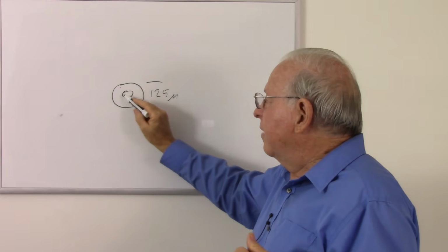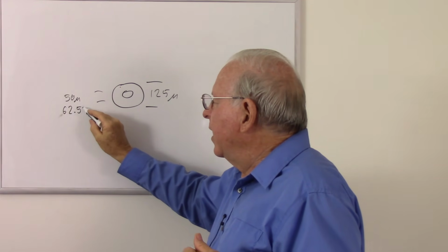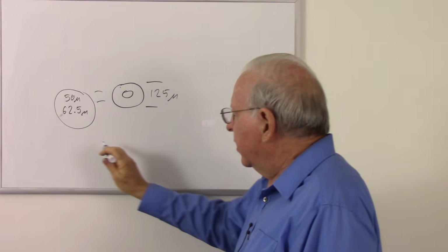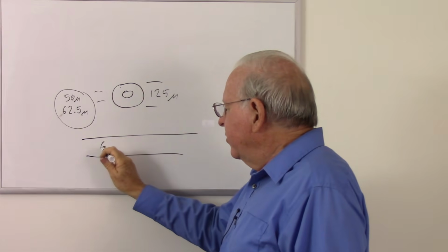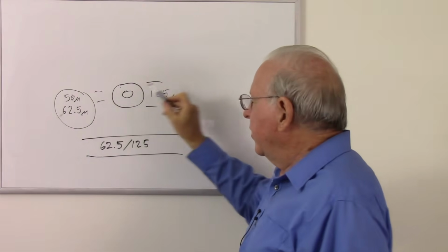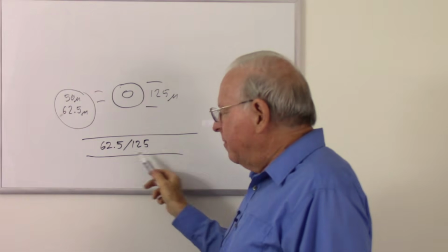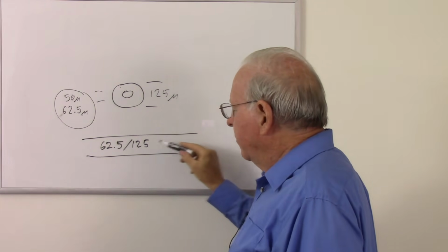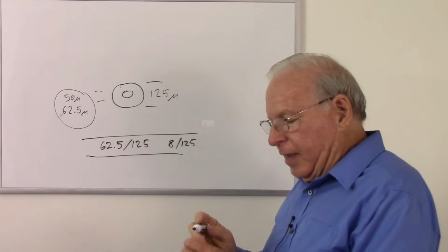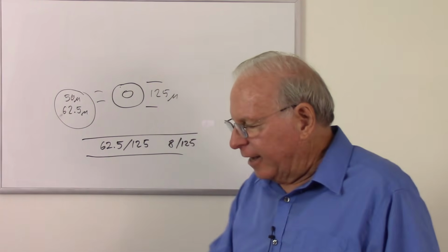Your multi-mode fibers tend to have a core of around 50 microns or 62.5 microns, rarely larger. Those are the sizes I see most often specified. In fact, if you look at the cable, somewhere you'll see something like 62.5/125. What do you think those numbers are? That's the core size and the cladding size. I saw a cable in a thrift store and I found a piece of fiber optic cable and the numbers didn't make sense, so I'm not even going to talk about that. But that's something typical. Or if you see 8/125, what do you have? You know you've got single mode fiber. And most fibers are going to be graded index, so they don't need to specify that on the jacket.